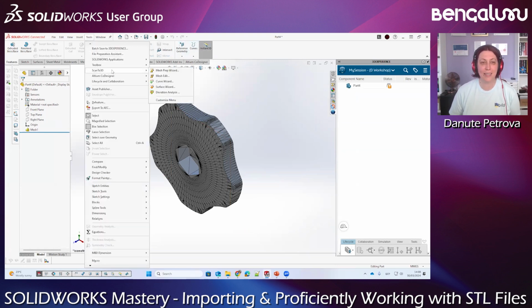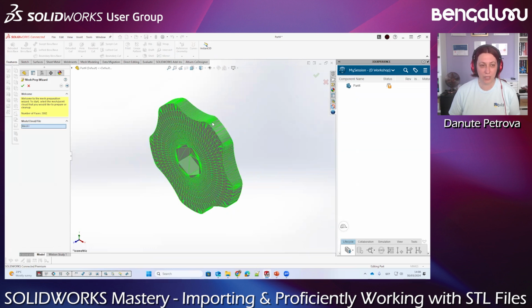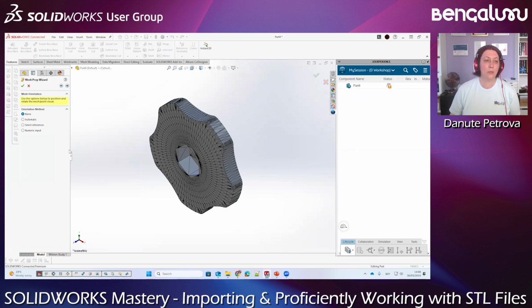Then you go to Tools and Scan to 3D, and you have this Mesh Preparation Wizard. It's asking you to choose the mesh cloud file you want to convert. I choose this one. First step is to change the orientation of your model. I would say don't do it from here. It turned out, especially with this knob, if I change the orientation from this screen, it's not translating the faces correctly afterwards. So better leave it like this, convert it, and move it afterwards. Don't use this screen here.